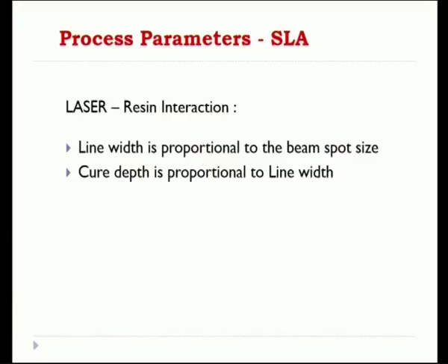In another slide I'll show you how much time we give for the exposure. So we cannot play around with varying the laser input or output. For example, if we need 100% for only 10 milliseconds, it should be exactly 10 milliseconds, and the exposure time and the input power are supposed to be 100% the same for all the layers, right? So these two parameters are very critical compared to the interaction. Once entered, it should automatically cure the required depth.